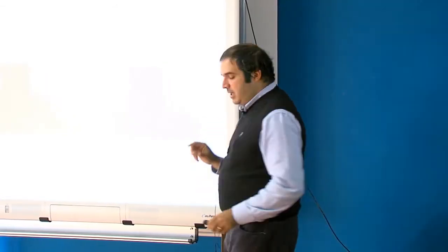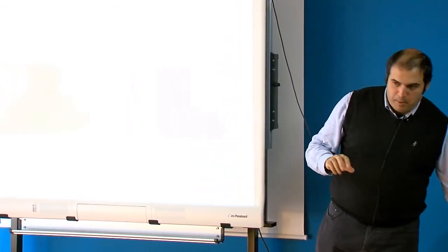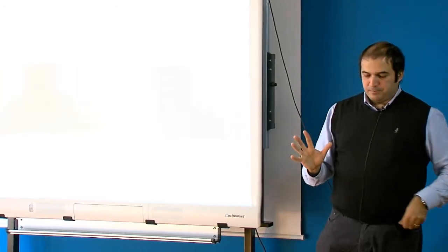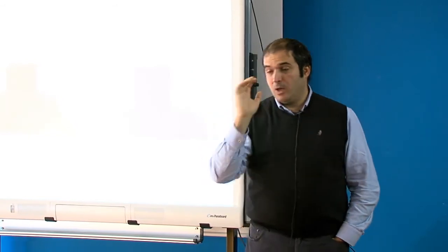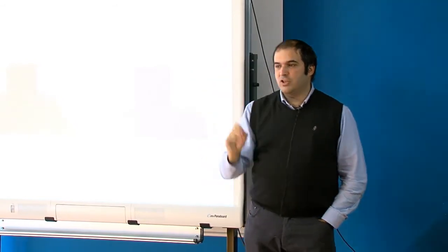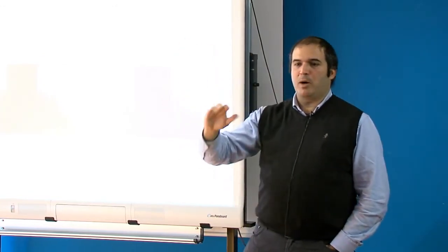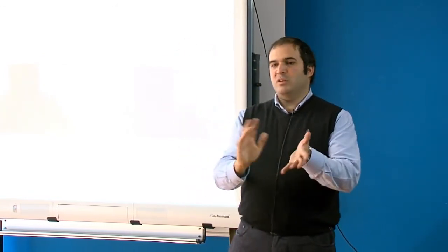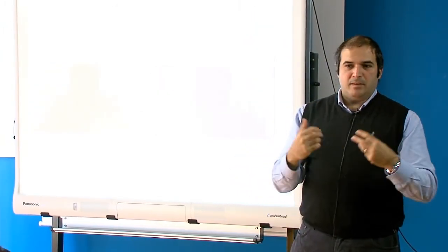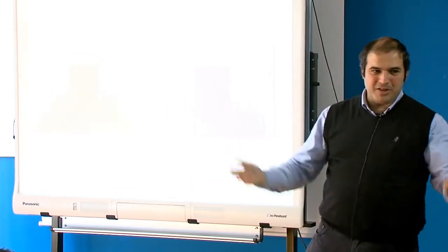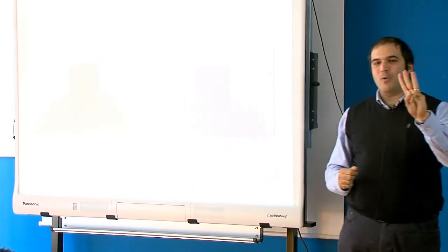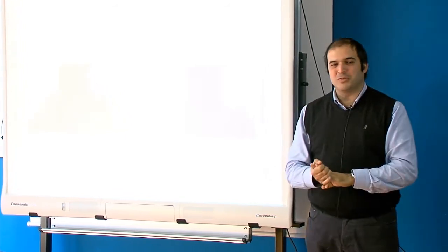Let me also say here that power amplifiers for base stations were used mainly for one-tone GSM. So people were using one carrier GSM with a power amplifier. The power amplifier says maximum input power 2 watts, and they were using that at 1 watt. Imagine this: with the increase of channels and mobile communication, they said, okay, now I want to send 3 GSM signals to the air.